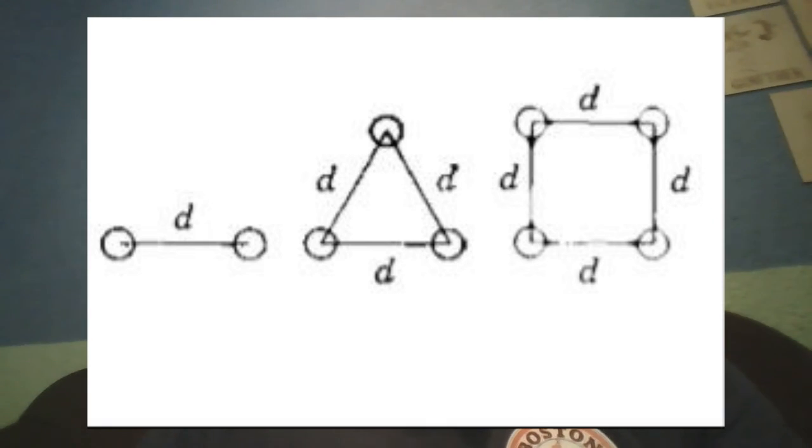Inductance calculation for bundled conductors. At extra high voltage, EHV, that is voltage above 230 kV, corona with its resultant power loss and particularly its interference with communications is excessive if the circuit has only one conductor per phase.